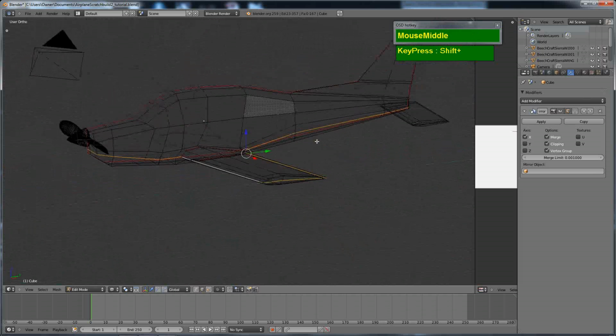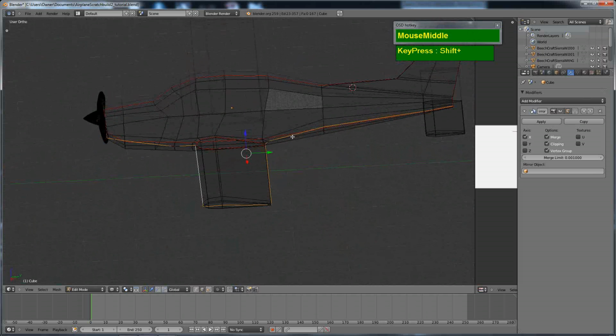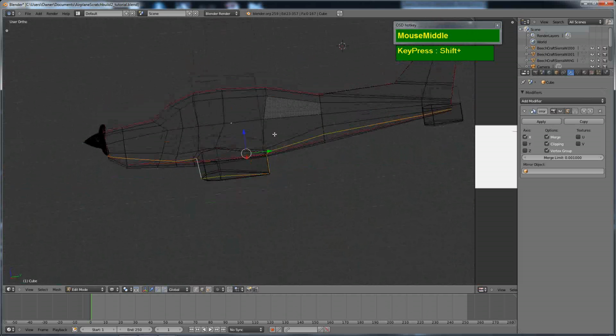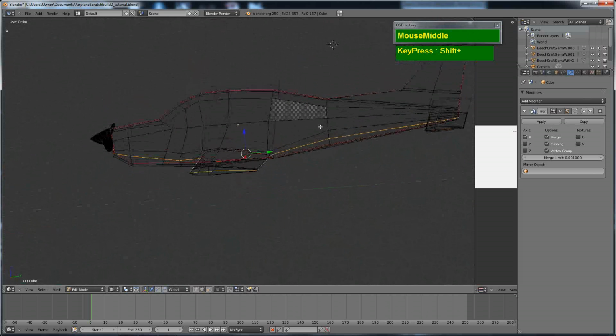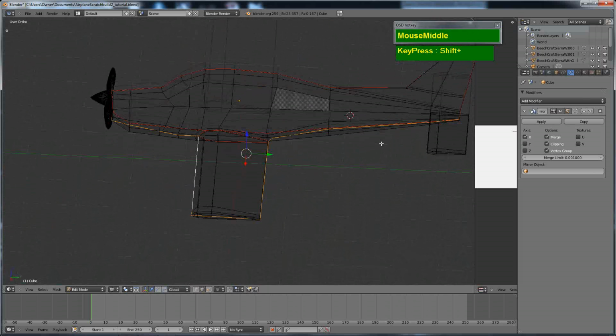What we're going to do is deselect these edges here by using the circular selection tool. As the name suggests, the first letter of circular is C, so you press C to bring up the circular selection. To deselect, you just middle mouse click. It almost behaves like a paintbrush. To increase and reduce the size of the selection, you just use your middle mouse, and then middle mouse click and drag and paint. To get out of the circular selection mode, just right mouse click.